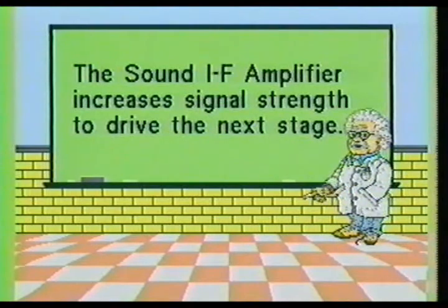The main purpose of the sound IF amplifier stage is to substantially increase the power level of the frequency-modulated 4.5 MHz signal, so the next stage will have sufficient signal strength to function properly.